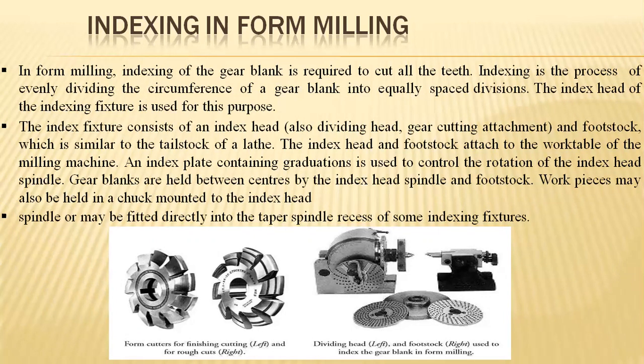Indexing is the process of evenly dividing the circumference of the gear blank into equally spaced divisions throughout its circumference. Particularly, this index head is utilized for fixing the number of teeth that divides equally over the work part throughout its circumference range.